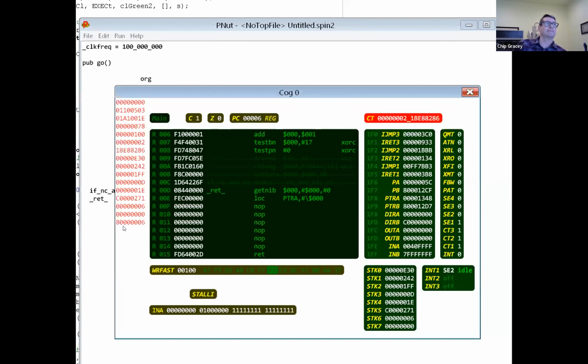Mm-hmm. So that's a packet that gets sent kind of under the radar through the debug system. And this whole thing works in real binary, not ASCII. So it's as efficient as can be. It's more efficient than normal debug stuff. So this is a snapshot that occurred at the break in one cog. It'll remain there, and as another cog, since it's running, gets a breakpoint, another window will appear. Yep. Oh, okay. We should try that.